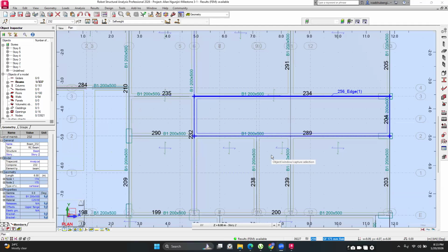If you are doing, say, majorly the high-end mansionettes, which have double volumes and columns with lengths of 6 meters, you need to consider that those columns may be slender. To know if the columns are slender or not, you can check manually: take the effective length of the column and divide it by the radius of gyration. Whether columns are slender or stocky majorly affects the failure modes.